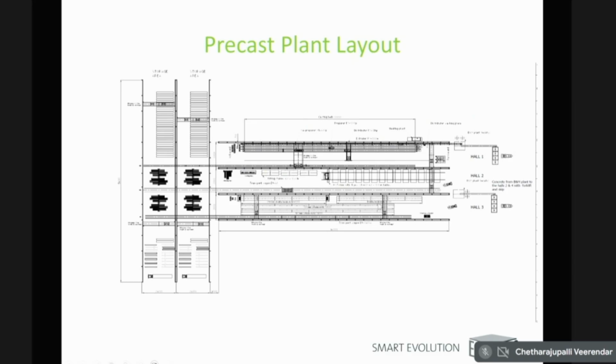So in the production yard, we are providing transportation wagons to move out the material which is produced and cured already on this transportation wagon, which goes directly into the stockyard, as you can see here and here and also here. There are 3. This is the slab production area, which you call hall 1, where you are producing pre-stressed hollow core slabs.